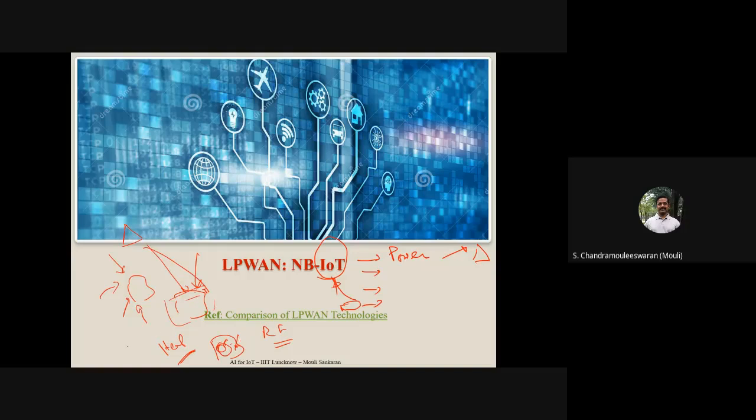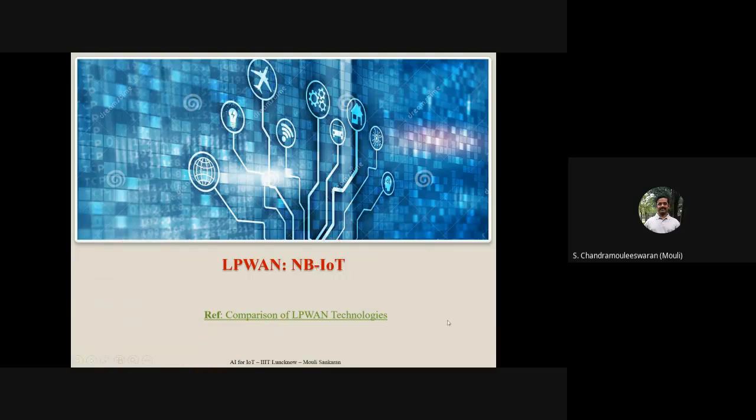Or in a harsh environment, it could be on a mountain over the Himalayas where the temperature ranges from minus 50 degrees to maybe 100 plus degrees. That is called industrial range. So we need to comprehend all these things before choosing a device, before choosing a technology. When we are designing something using IoT, these are the restrictions that we get while deciding some communication technology for IoT.